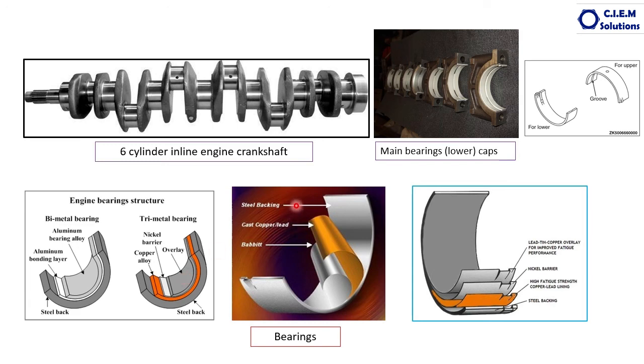And one more important thing we have to discuss here. You see this crankshaft main journal bearing; this bearing looks a little bit different. This is with some kind of collar. This is called a thrust bearing. Why is this thrust bearing designed? When the crankshaft is rotating, it tends to move to and fro a little bit because it is rotating freely on the journals.